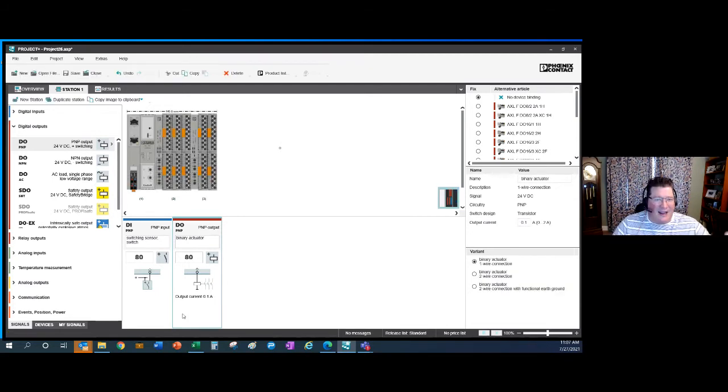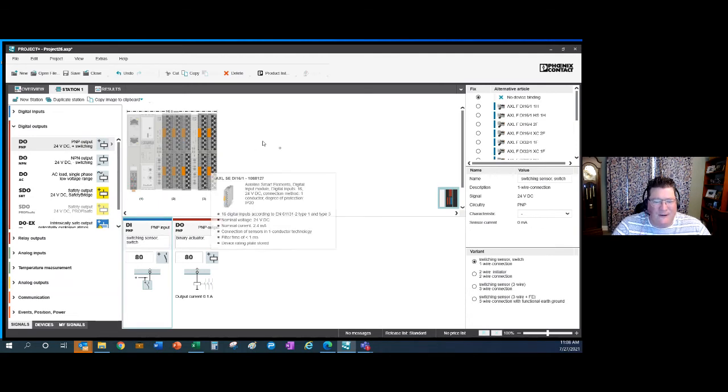So now you can see I have an I/O station that covers both my digital input and my digital output needs. And then I can even go one step further. By default, it is going to choose our highest density, lowest cost options. But in my application, maybe I don't always want the highest density. With the highest density input modules, I'm only going to give you a single terminal for your digital inputs. Maybe I don't want that. Maybe I want the extra 24-volt connections, or some of the extra 24-volt and ground connections for my input signal. So what can I do?